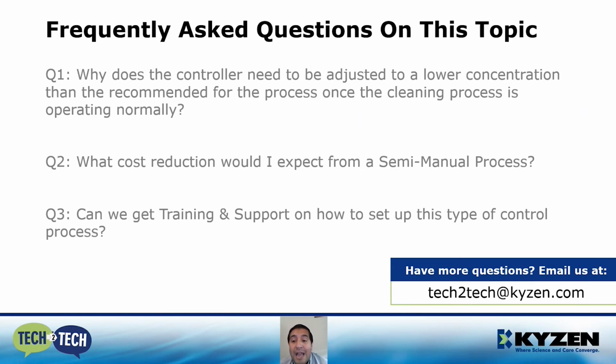The chemical has a much higher boiling point, so fewer components of the chemical are being lost. Usually, we lose more chemical through drag out than we do through evaporation or the exhaust. Therefore, over a long time, we would have to replace more quantity of water than chemical. This is why we initially set the controller to have the desired concentration that we want to keep in the process. Once it is fine-tuned to your specific process factors, that set point might be higher or lower than the reference that we just gave, but it is a good baseline to start.